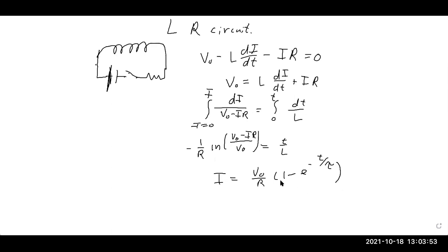We have a very, very similar looking solution to the problem with just a capacitor and a resistor, where this time, instead of building up energy in the charge on the capacitor, we're building up energy in the current through the inductor. Excuse me real quick, what is the symbol under the t there after the e? That's our time constant, tau. Okay, thank you.